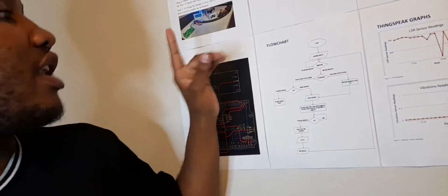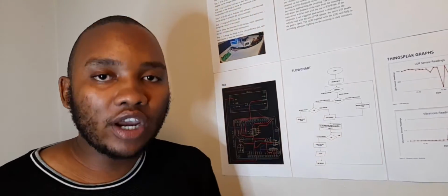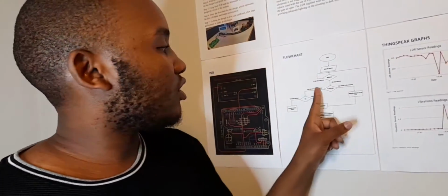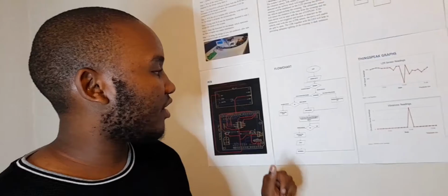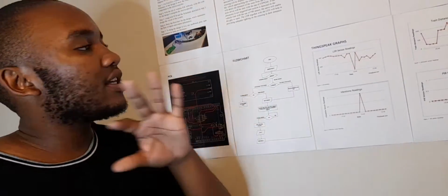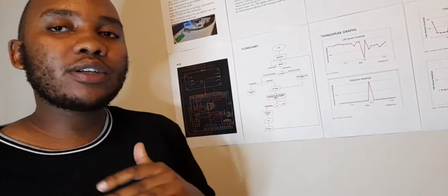Explaining now the flow of the system: if the vibration of the train on the railroad is detected, then the ultrasonic sensor will be triggered, and when it is triggered, a warning is displayed on the LCD, and then the servo is activated and the gate opens. If the ultrasonic is not triggered, but there is a vehicle on the road side, the PIR will be triggered, and then the servo is activated, allowing the gate to open and vehicles to cross over.